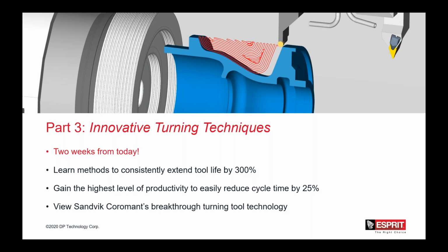That's one of the topics that Kevin talked about in the beginning. There's a checkbox in the hole recognition dialog for having a hole to be machined at the active work coordinate. So if you want to recognize a hole at the active work coordinate, you would leave that box checked. And if you want Esprit to pick up the holes at different orientations, you would simply uncheck that box.